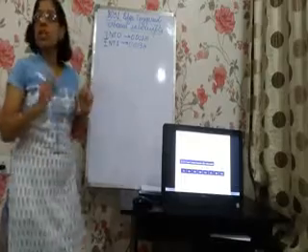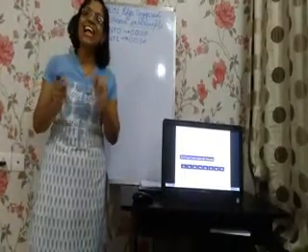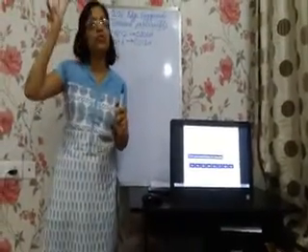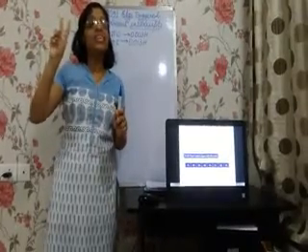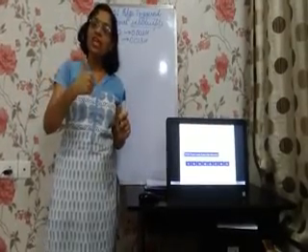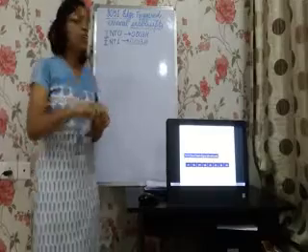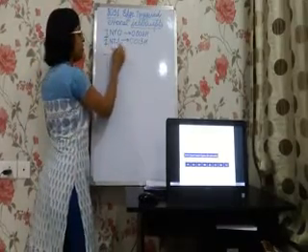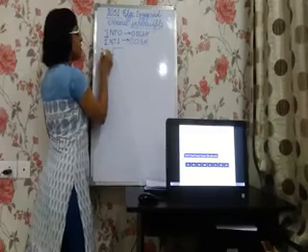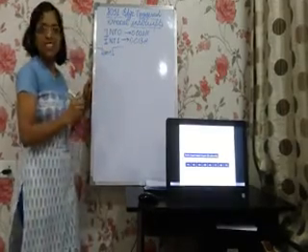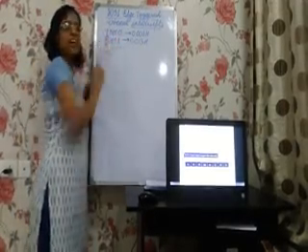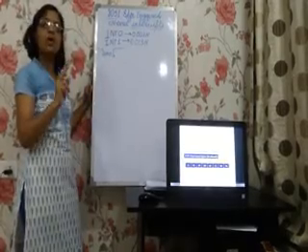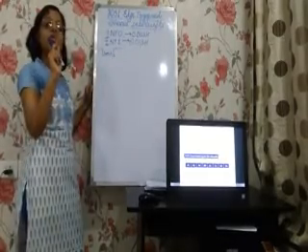Now these interrupts can be defined on the basis of two things: how they are triggered, whether on edge or on level. External interrupts can be triggered on level, meaning a low level triggered interrupt. Upon reset, these two interrupts INT0 and INT1 are always defined as low level triggered interrupts.